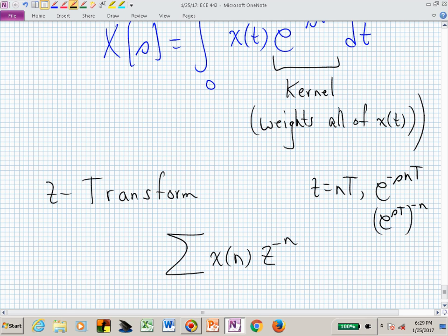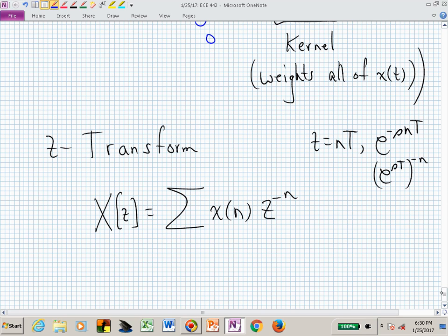And we may talk about different sidedness of this z transform. Let's just now say this is our capital X of z. But we might have this defined only for non-negative values of n, or for n equal to 0 to infinity. This is now one-sided.